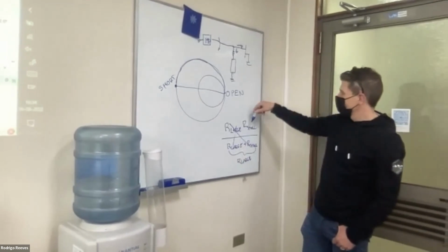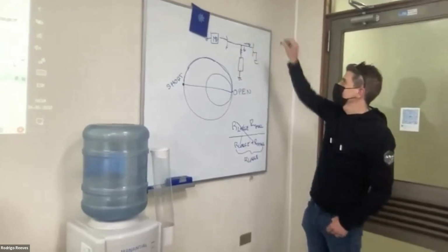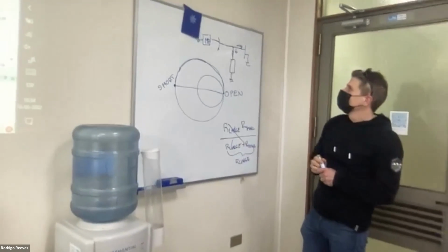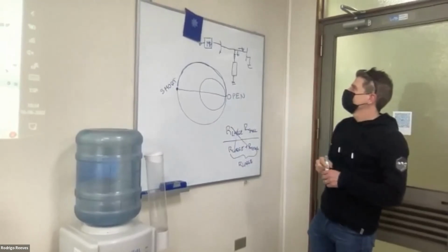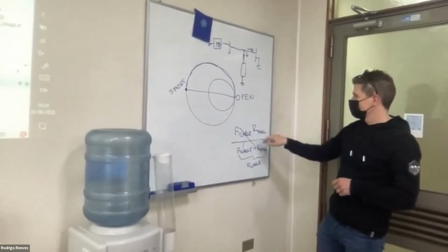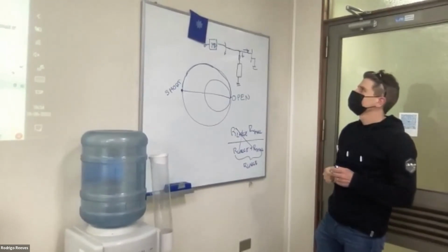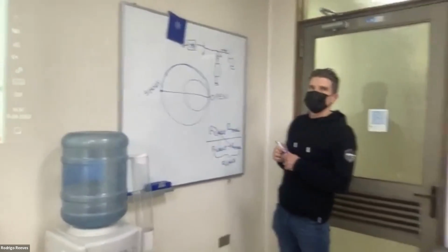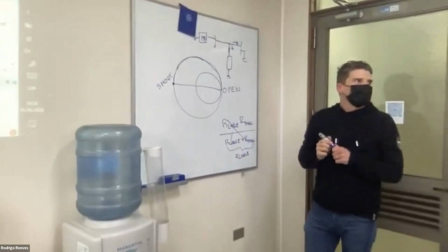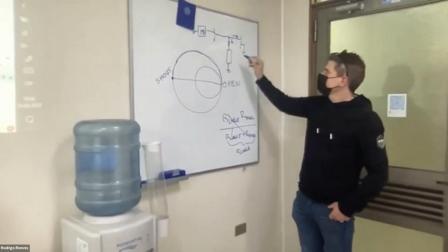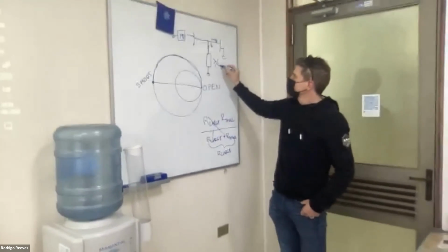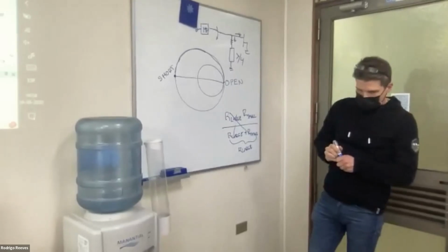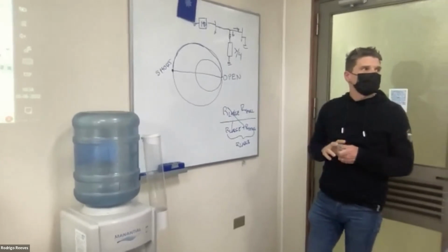So we are left with R small. So it goes there, thinking of the way the signal wants to go, even in a basic circuit. So that's why I can add it here. So it must be, what, 20 times the series resistance, something like that? Maybe. Yeah, that would be a good rule of thumb.